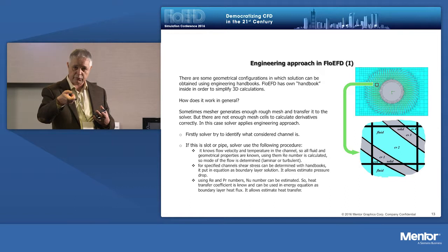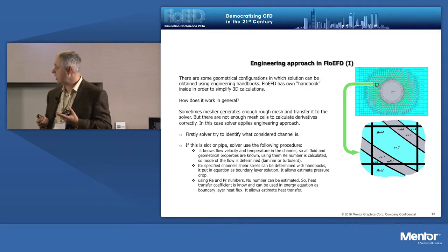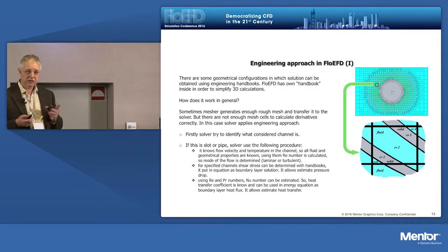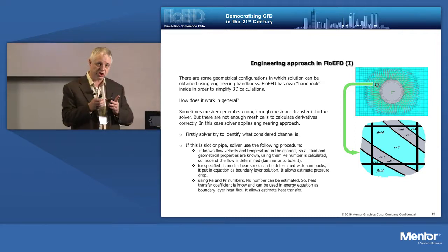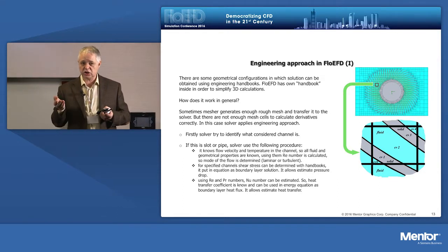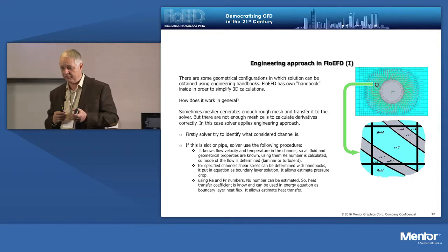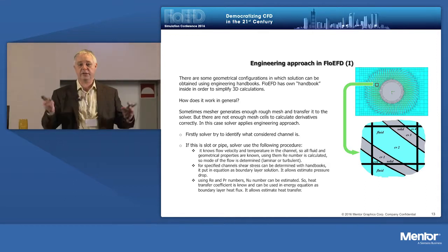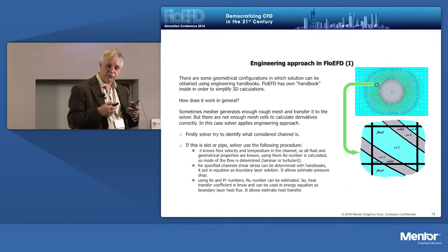And if we see that the number of cells is not enough for the full resolution, we can come into analytical solutions. And again, we can do it in a fully automatic way. And then we understood it's also a big advantage for our technology that for some dedicated situations, which can happen, for instance, for some heat exchangers, for selections of pipes, or with some heat sinks, it's happened very often, we can substitute our 3D solutions by analytical solutions. And we are using this.